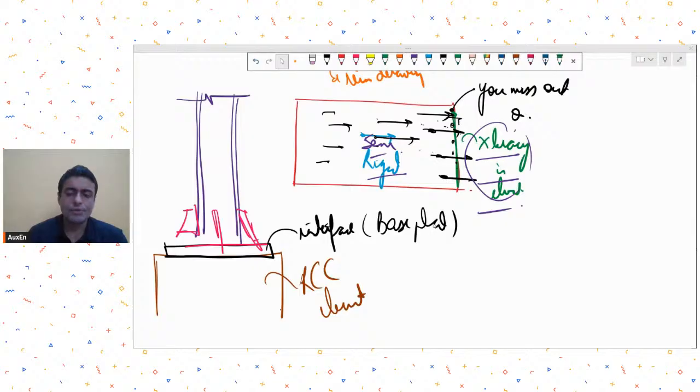And usually the base plate size is governed by the bearing in concrete. The bearing strength in concrete is quite substantial. And if you have a 40, 50 story tall building, the steel columns themselves will have quite a large size.